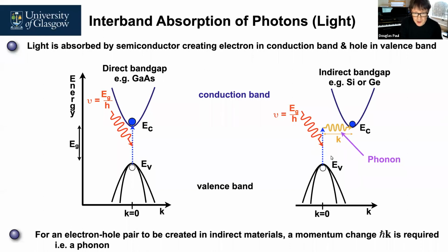to allow us to absorb light from the sun. So in fact, direct bandgap materials are much more efficient at absorbing photons of light because they don't need heat to convert them into electricity and to generate the electron and the hole pair, while something like silicon needs a bit of heat, and that makes them less efficient as solar materials. Now we'll talk about how much of an efficiency difference that actually is a little bit later in the lecture, but that's the basics you have to understand.